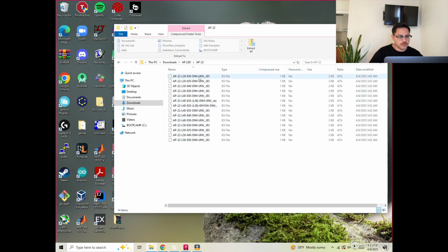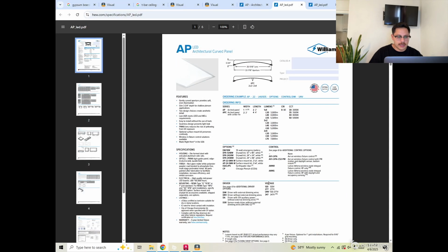Okay, I see some of the things right here. It's called dimming, universal. I kind of have a picture of what that means already. If we come back, it says right here, do you want dimming? Universal probably just means the voltage that you have at this job site. These are things you have to determine while at the job, like what type of panels they have, and whether they even have 277 at this place. Typically they do, but you should always coordinate with your PE or your project manager, whoever you're working with, to determine what type of voltage you have at that job site.